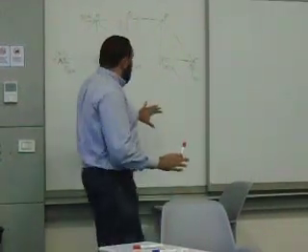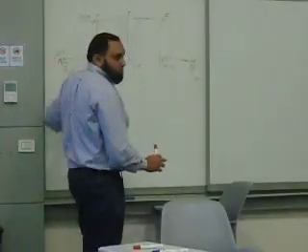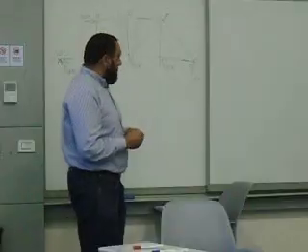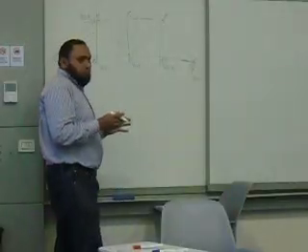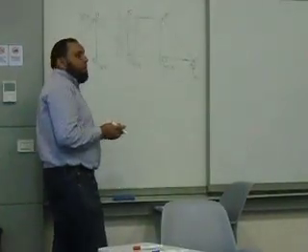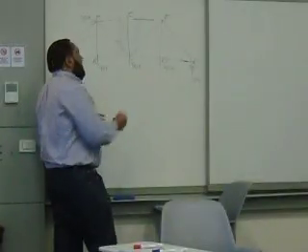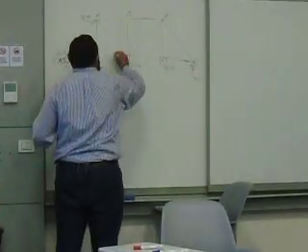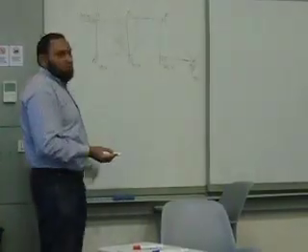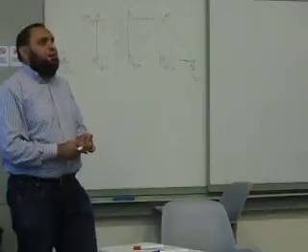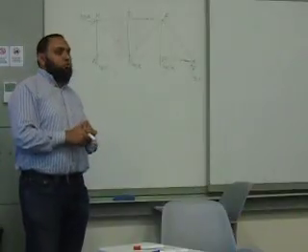This is after getting the reactions. Okay, and I got the reactions already from you. So I'll cut a section passing through the members that I need. So in this case, it's these 3 because these are the ones required. Ideally, through how many members do I have?